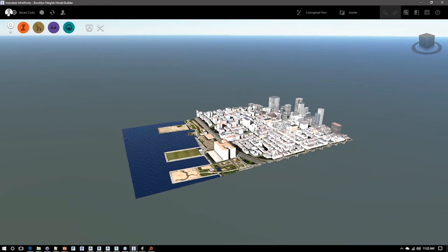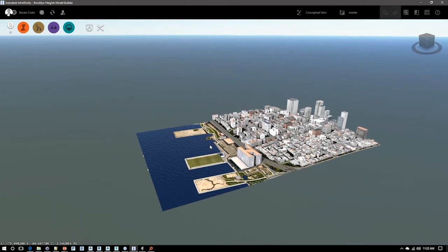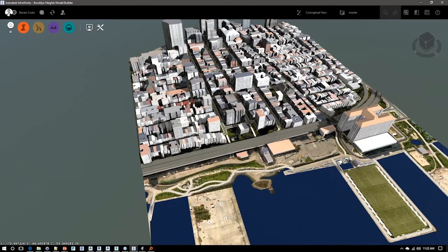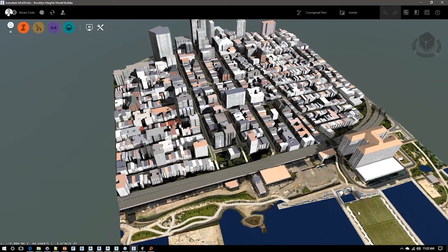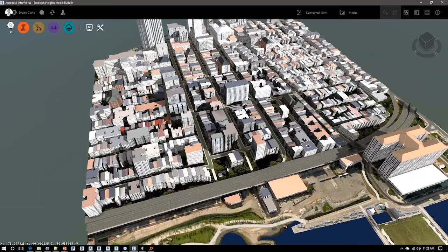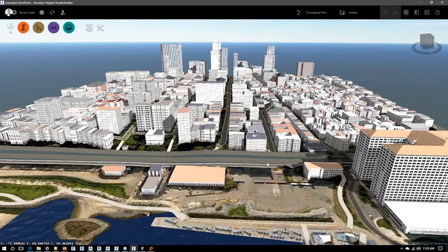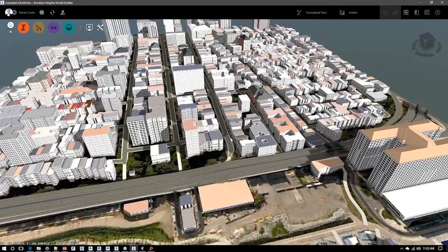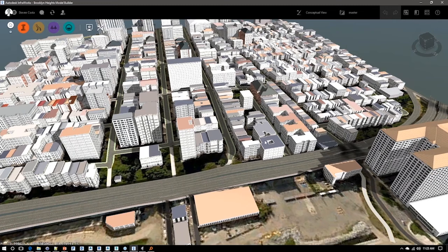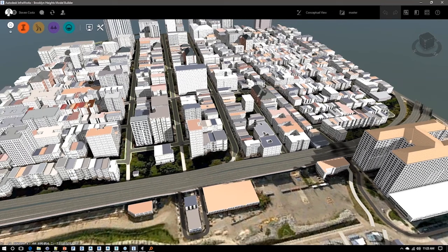I did this yesterday and brought in a 3D model. And you can see it's brought in information about roads, about aerial photography, about the buildings, and so on and so forth. Now, again, while this may be exactly what you need, others may want a more simplistic rendition of these buildings. The buildings themselves are just polygonal shapes that are extruded to a particular building height. That's part of the GIS data that's available.